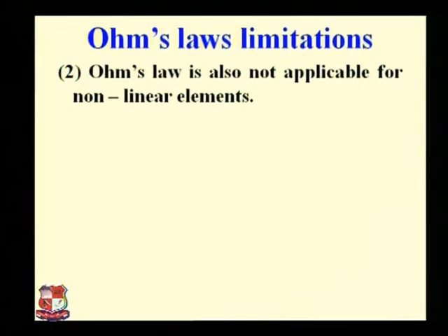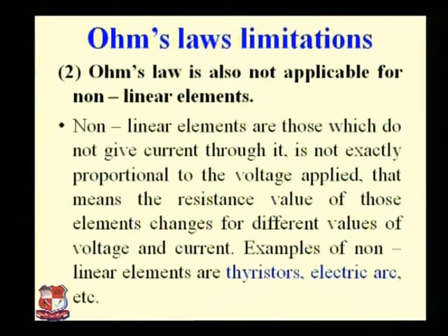Second limitation: Ohm's law is also not applicable for non-linear elements. Non-linear elements are those elements for which the current through them is not exactly proportional to the applied voltage. That means the resistance value of those elements changes for different values of voltage and current. Examples of non-linear elements are thyristor, electric arc, etc.